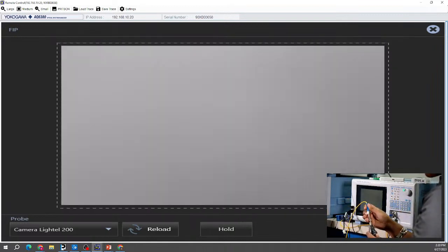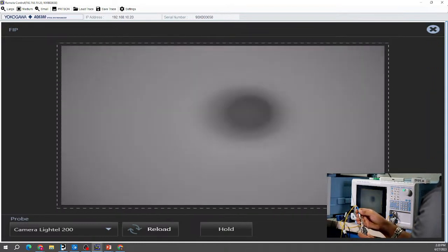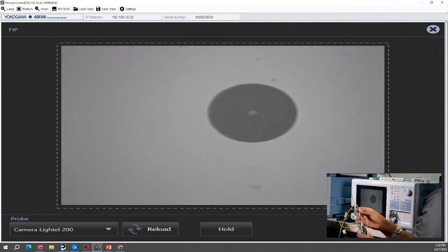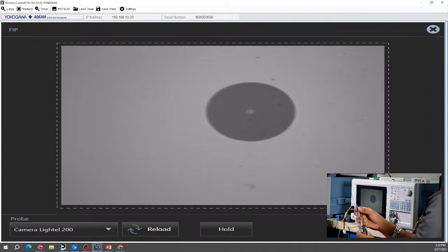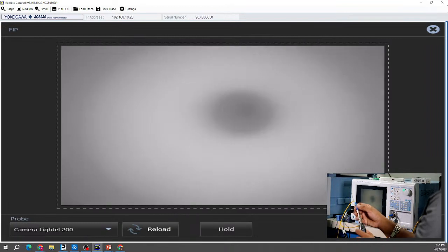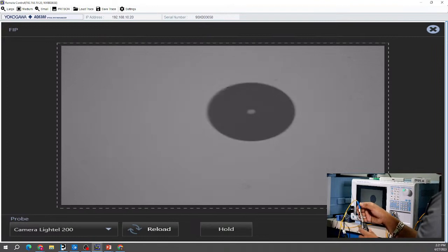So the reason for doing this, of course, is to make sure that your fiber is clean, not contaminated. You want to check that, especially before you plug it into the OSA, because there is a fiber on the inside, and you don't want to introduce any contamination or scratching of the internal single mode fiber that's inside the OSA. Okay, so we can see the fiber is a little dirty, but mostly clean. I'll make sure to clean that better. It's as simple as going to that app menu and pressing it, and quickly, on the go, checking the fiber to make sure it's clean for optimal results.